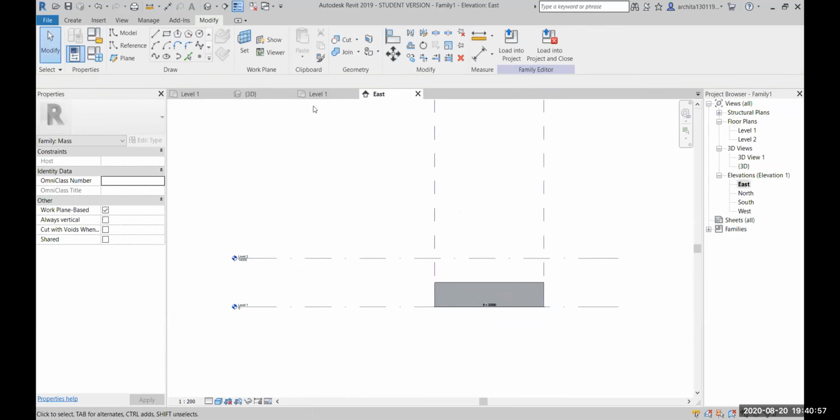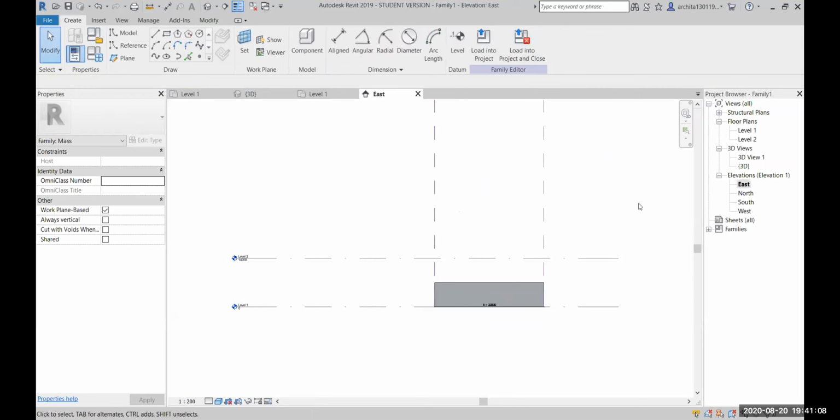Okay. Now, how? Right now you went to create and created a plane, right? I went to create, level, and then created the plane. Yeah, but instead of creating a plane, what if I just press control and copy? Then you know what will happen, Pranali? When you copy this level to another height, it won't get reflected over here. It doesn't get reflected in your floor plan.